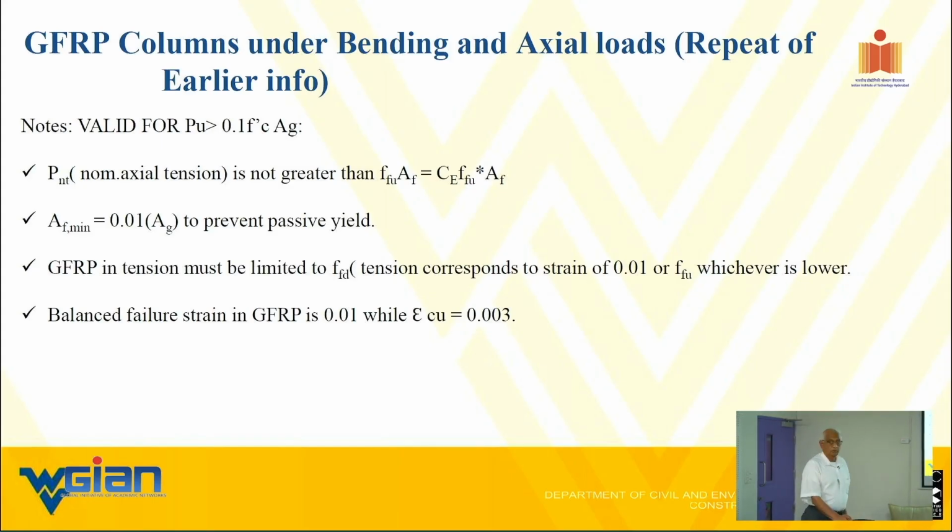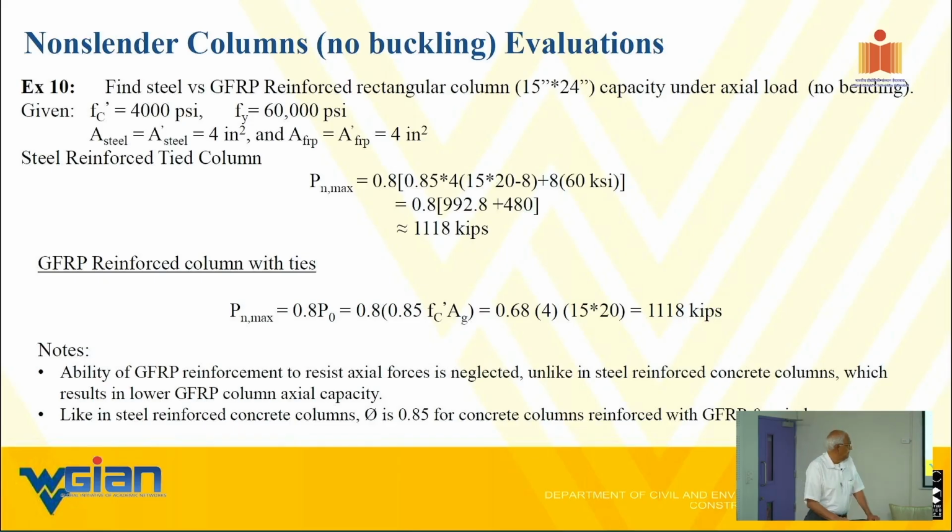Sir, in the previous slide, where did we consider both the reduction factors? Where are the separate reduction factors, like for the material and another 0.8 and 0.85? Right there. 0.8 and 0.85. The former 0.8 is a general reduction factor because of our basic uncertainty.